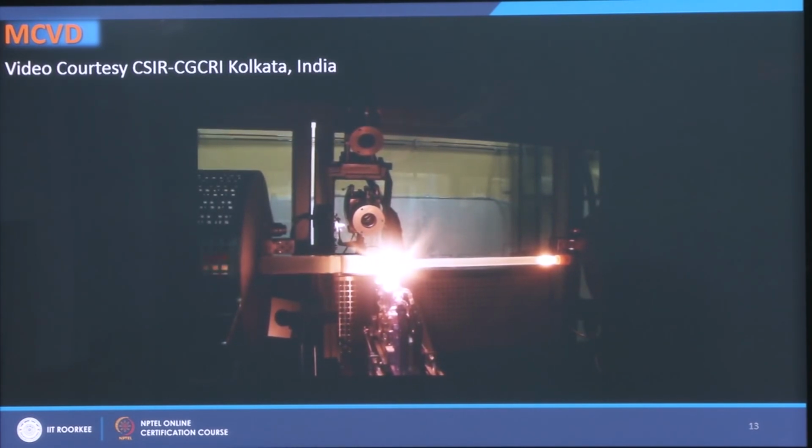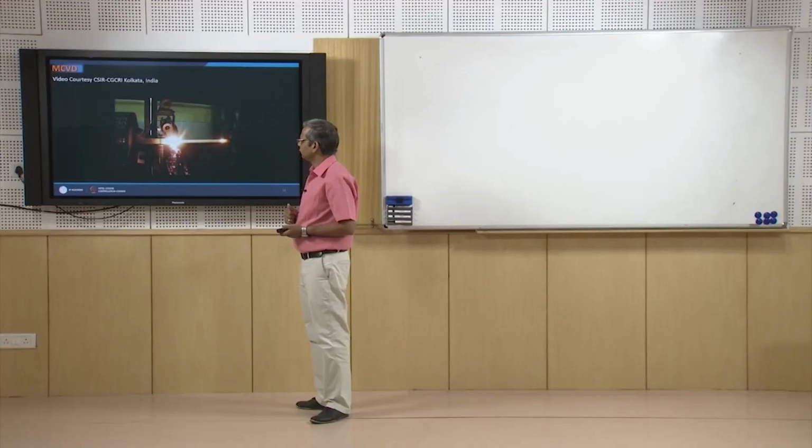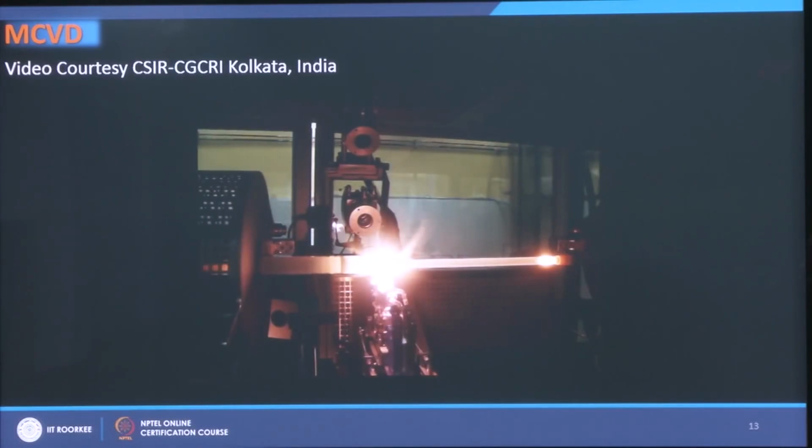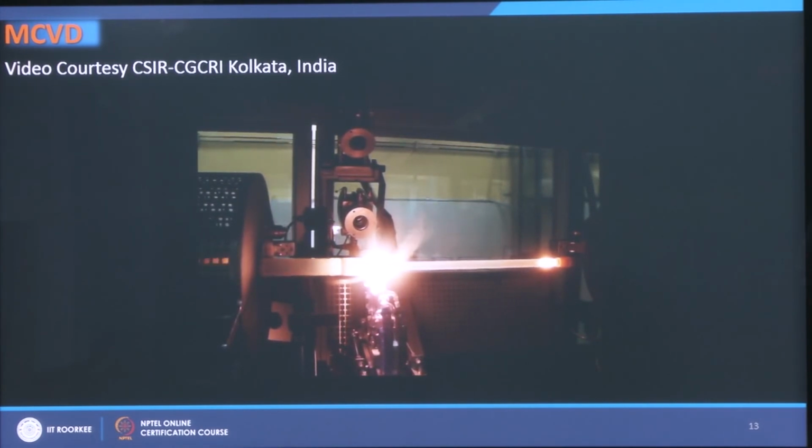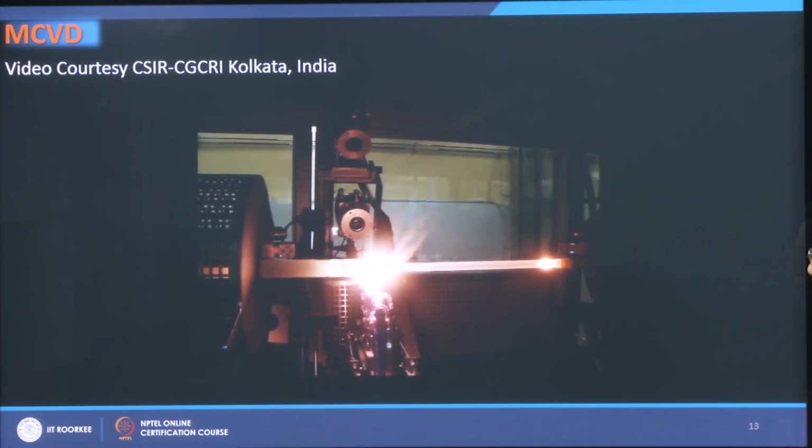Here you cure the coating. Either you can have a coating which can be cured thermally, so you have a curing furnace. Some coatings can be cured by UV, then you will have a UV lamp assembly here. Finally you monitor the diameter of the final fiber, and then you take it up on a drum.